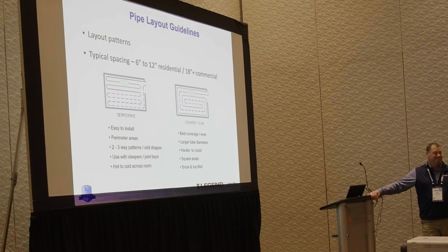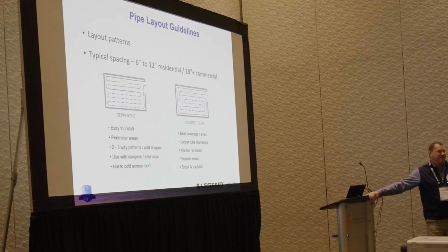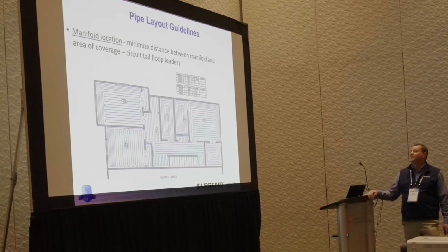But I'm like, do you really get a significant delta T? We want to do that, but realistically, in practice, with a counterflow, we're talking about 1 or 2 degrees of difference. Somebody said it was the best way to do it, and so people have followed that practice because it was the best way to do it. But it may not be practical to do it that way.